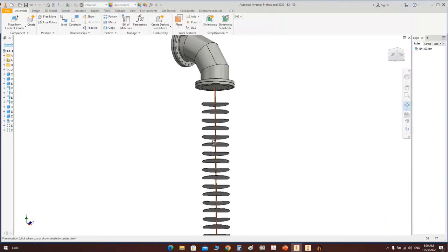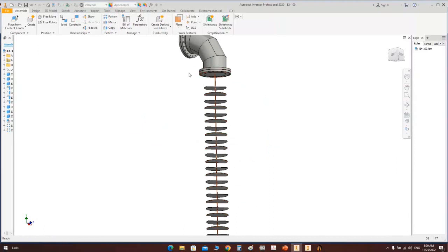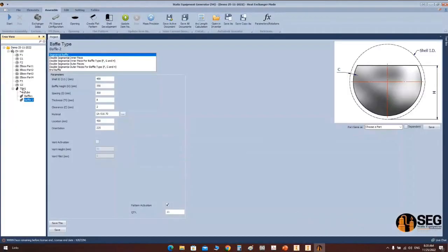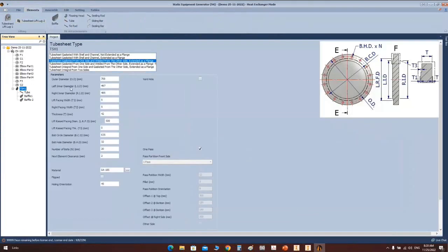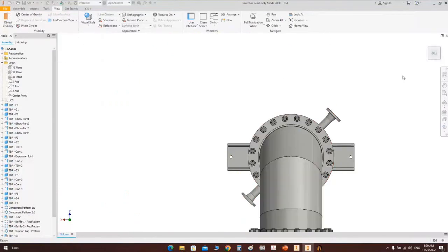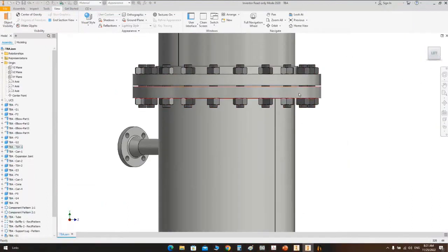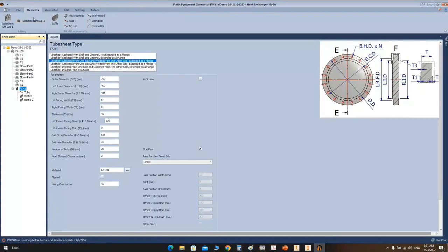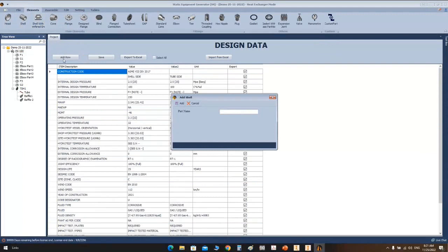Let's add the other items like shell, the second tube sheet, and after that proceed with tube sheet holing and tube pattern. So from here, let's select panel 1, and let's add the next element, which is, let's remove this section. We have a shell course here after the tube sheet. So from here, let's select the vessel, and from elements, let's add can. So let's add can.